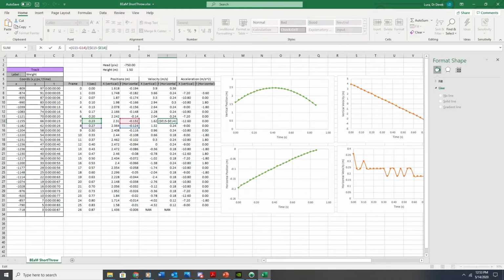For velocity, you see a couple of those there. And then I can do the same thing using acceleration. And again, acceleration uses a backwards difference, so rather than using the next value, I use the previous value. And again, that helps with that offset area here, where you can see I lost the last value because I don't have a next one, and then for acceleration I've lost the first value. So rather than having two missing values at the end, I have one missing at the end and one missing at the beginning. And so you see I have my position, velocity, acceleration data.